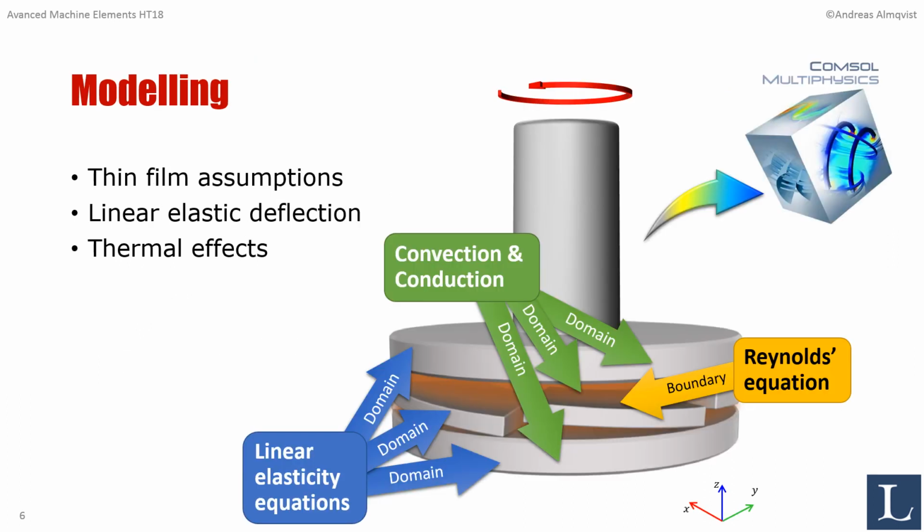So how to model this kind of application? If you have the possibility to use a software like COMSOL Multiphysics, that will allow you to couple a different set of physics. For example, in this case, you probably would like to couple linear elasticity equation, solid mechanics, with convection and conduction, which is going on inside the film and inside the material.